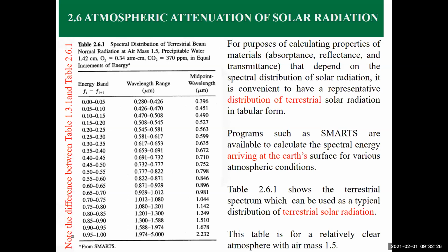Whereas a shiny surface would have absorptivity almost 0, but the reflectivity greater than 90%. On the other hand, glass is going to have a transmissivity closer to 1, 0.9, 0.93, and then the absorptivity and the reflectivity are almost negligible. So now it depends on what your target is. Is your target to absorb the energy, to reflect, or to transmit?